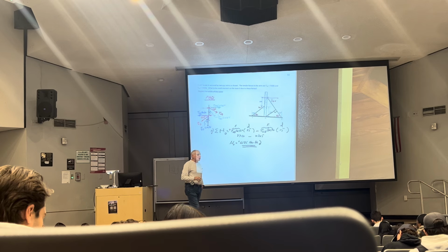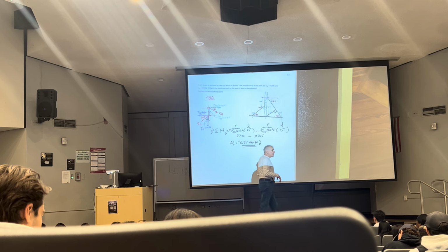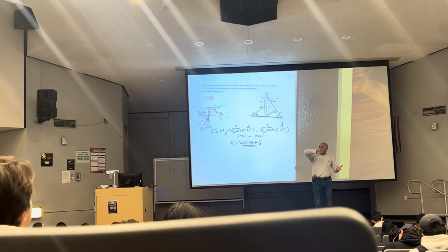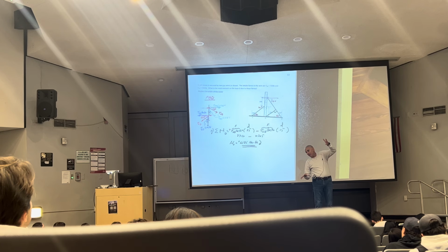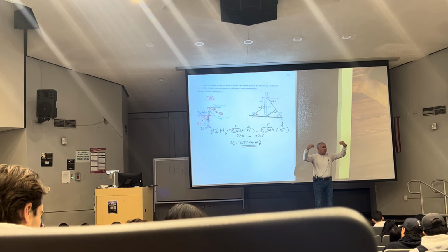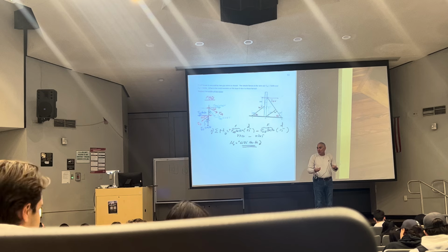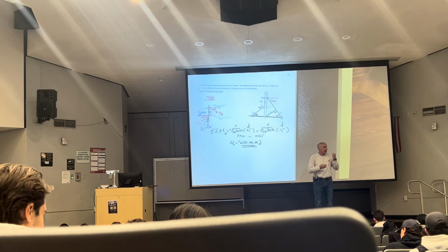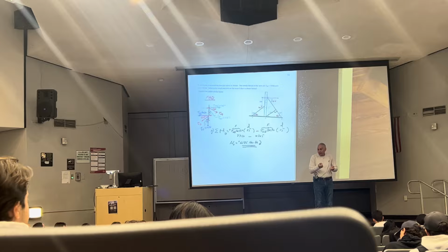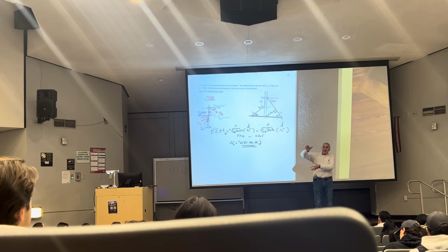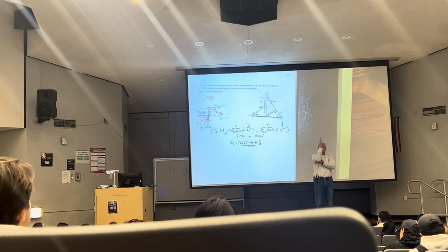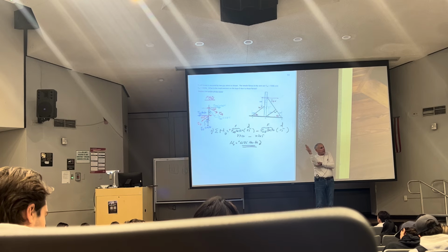So these moments are trying to pull this clockwise. So if it's going to go, it's going to rotate clockwise as it falls. Now, if it's to stay there, what must the ground do? It must create a 6,185 pound-feet moment that is counterclockwise for it to stay put. If I don't produce that, then you'll see it go this way.